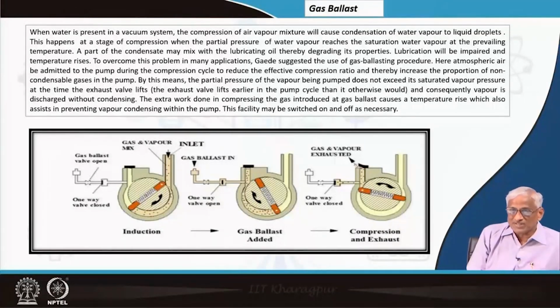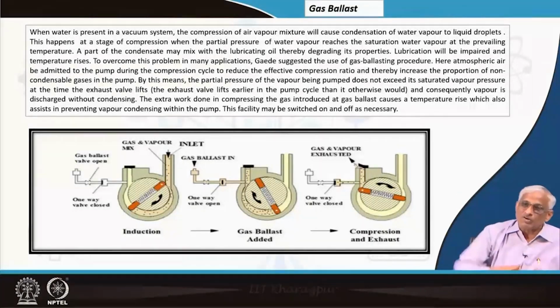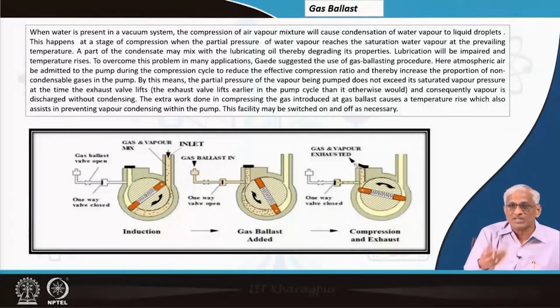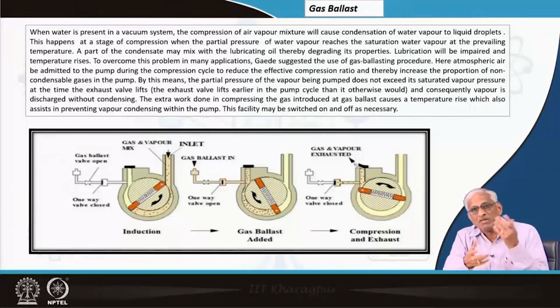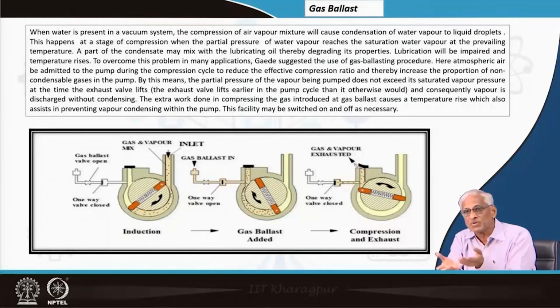Then droplets follow the gravity rule. They do not go upwards. So, they will never be exhausted, and again it will come back and it will evaporate once the vane crosses, re-evaporation. It will be a continuous process. You will never get better vacuum than the vapor pressure of water at room temperature, let us say 20 torr. So, pump is running, you are supposed to get minus 2 torr, you are getting only 20 torr.